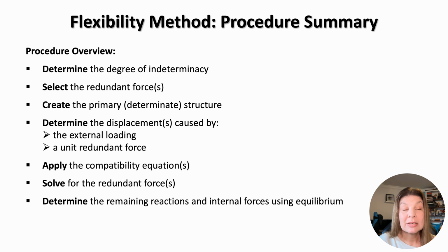Next, we applied the compatibility equation to determine the value of the redundant force. And finally, once the redundant force had been determined, we returned to the equations of equilibrium to calculate the remaining reactions and internal forces. This is the complete flexibility method procedure, and it is the same sequence of steps that we'll follow regardless of whether we're analysing beams, trusses, or frames.